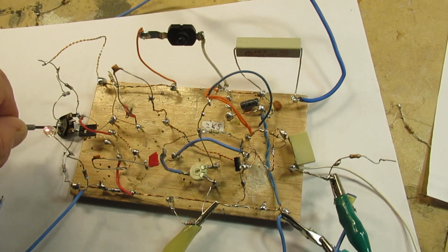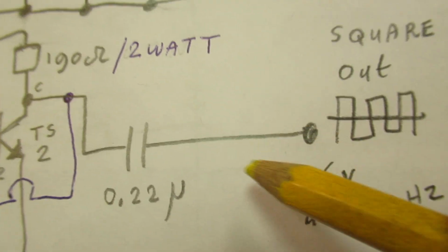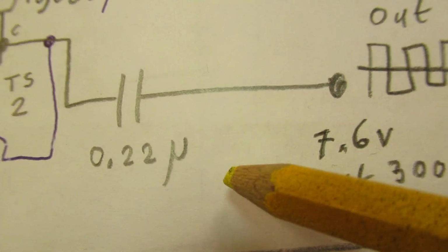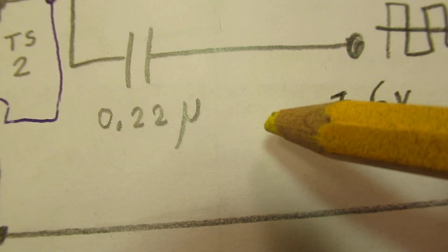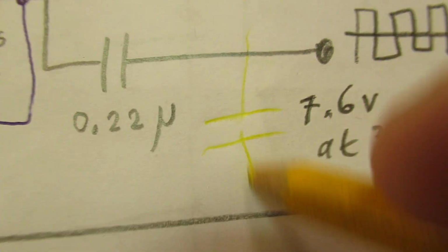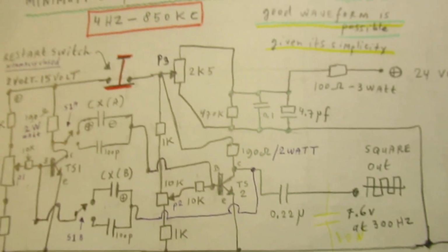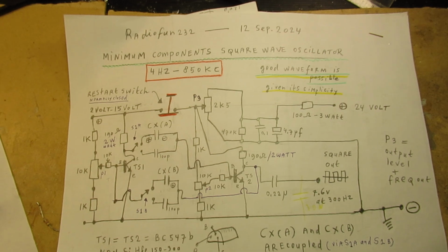it's useful. By the way, I have to tell that I mounted here a 10 nanofarad capacitor, and now I have these results. Say that 20 megahertz or so, or not 20 megahertz, completely unreliable. So here is that gap of 10 nanofarad. Anyway, in a certain way, I have to say, don't believe me. Do your own experiments, etc.